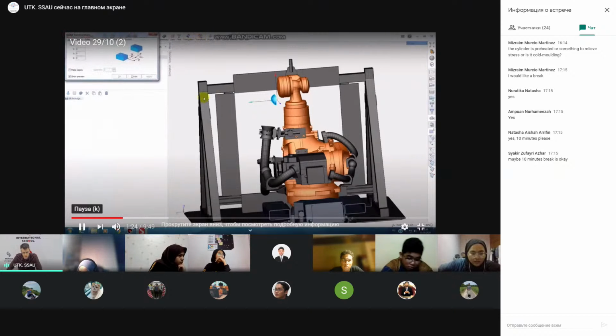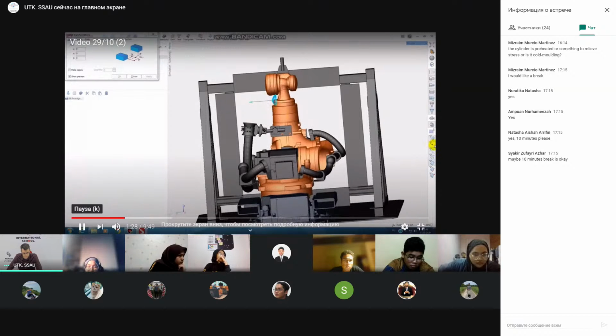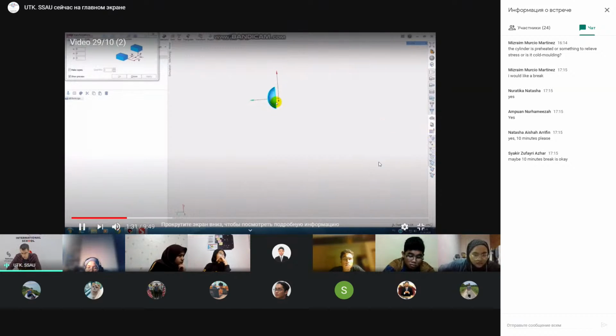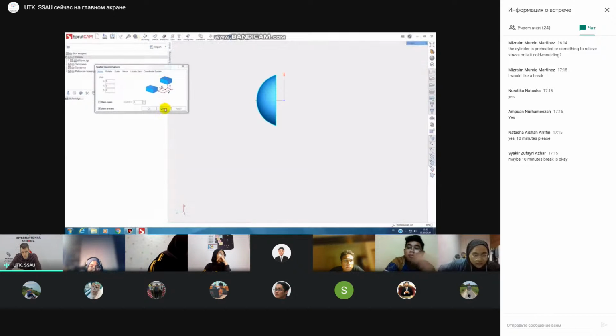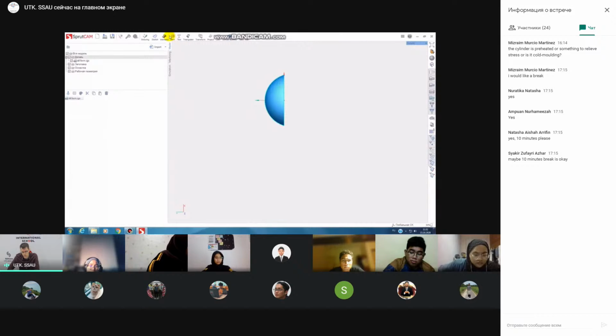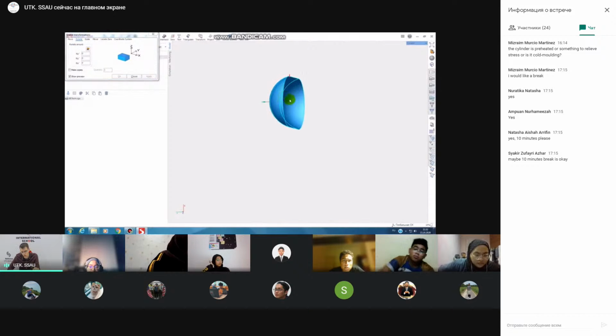For this we use transform button. By using the buttons on the right menu, we can remove the robot. It will disappear, so we can see only path. The first, we need to move the path to the center of the local coordinate system. You can see we have moved the path to the right. Of course, we need to make measurements, but for our practical case, you can make this by eye. For us, it's not so important tolerance of the final path, so we can make this by eye.